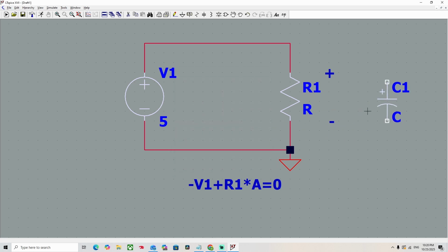So it would look something more like this, where this is your positive voltage and this is your negative voltage side. These kinds of capacitors are usually used in DC situations. This is very important because if you were to hook it up the other way around to a positive supply, you would actually blow up this capacitor.